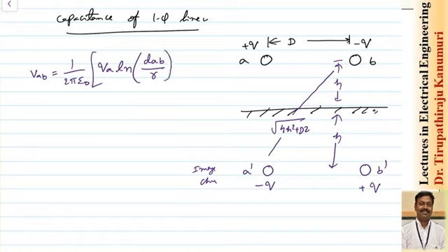So actually this is DAB minus R, but because DAB is very large compared to the radius, I am approximating it as DAB. It is not going to affect your result. Same thing is the case for QB into ln of the distance of conductor B with respect to B, which is radius R, and with respect to A, that is dBA.